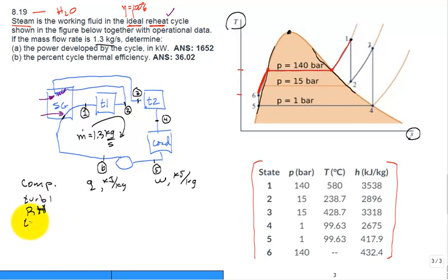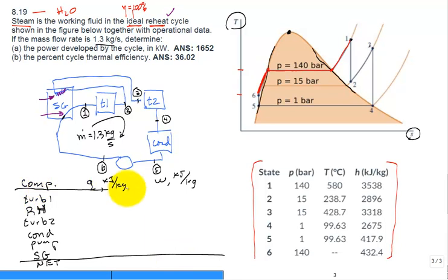And then the second turbine, and then the condenser, and then the pump, and then the first pass through the steam generator. And I didn't leave quite enough room, because what I'm going to do is I'm going to sum each of these columns and get a net. Then I'm going to make sure that Q net is equal to W net for that cycle. If they're not, then I look for an error. Okay, so you just kind of walk through this.